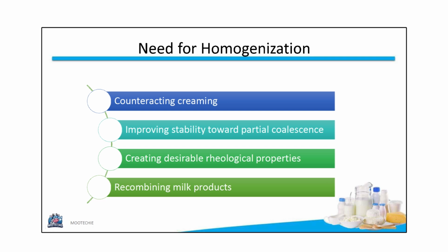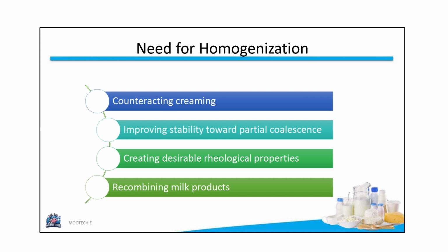The need for homogenization includes counteracting this creaming effect, improving the stability of the emulsion against partial coalescence, creating desirable rheological properties like mouthfeel, and for recombining milk products like milk powder into liquid milk.